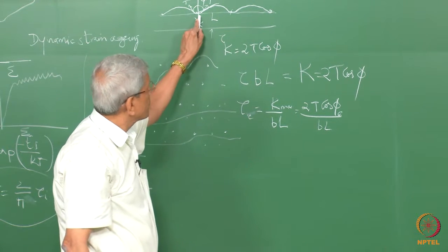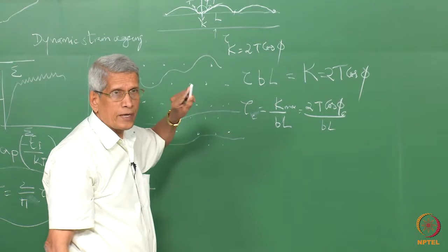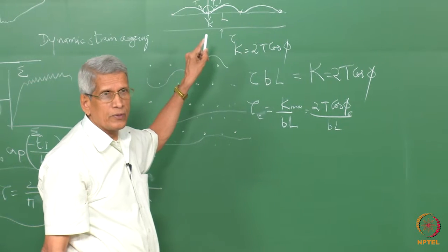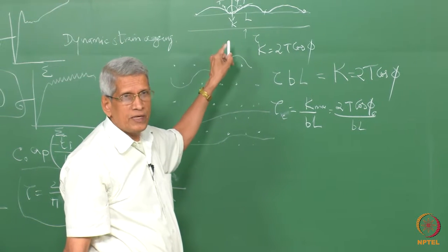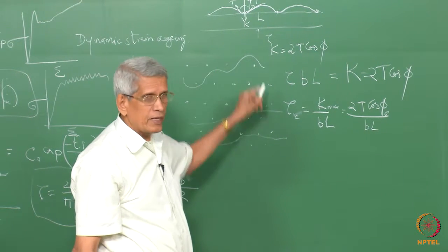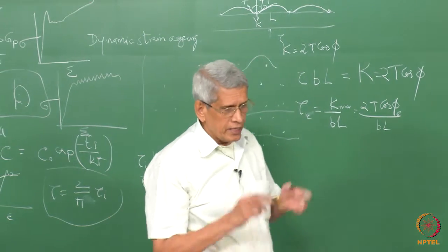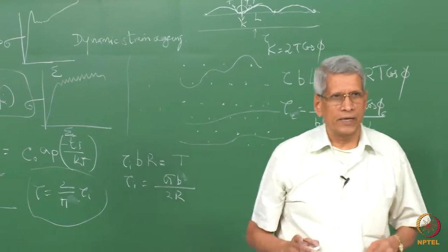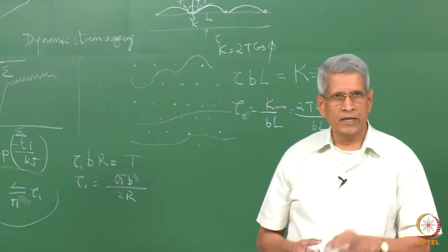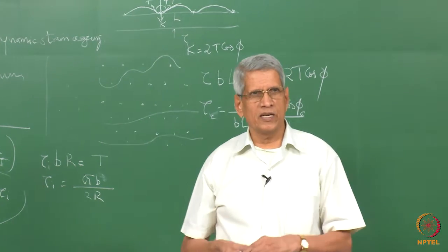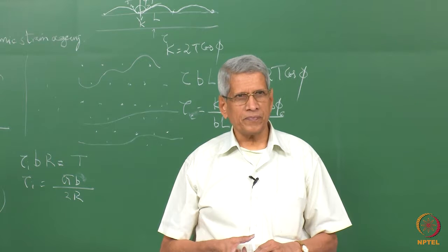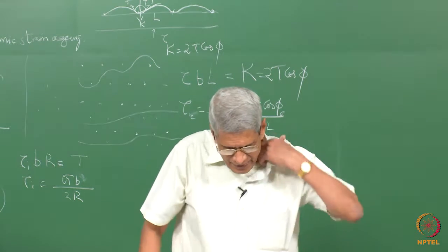And suppose it's not able to cut through the particle, there is another critical value at which it can loop around this particle. That will decide whether shearing or looping is the mechanism which is going to operate in this dislocation precipitate interaction, okay.